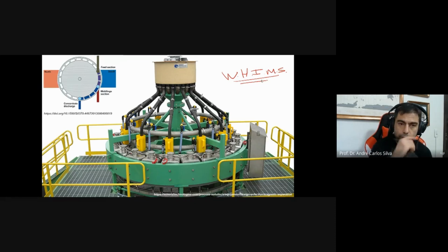How does this machine work? You have two poles, and here they are not quite visible to us, but in this picture you can see north and south. I'm going to feed my slurry in one place right here, at the beginning of the pole. During this movement, everything in here is turning in this direction. The magnetic material gets attached to this matrix. Those slots over here are not actually slots, they are the magnetic matrix. And when I'm leaving the magnetic field, I add water at this point, and then I wash away the middlings.